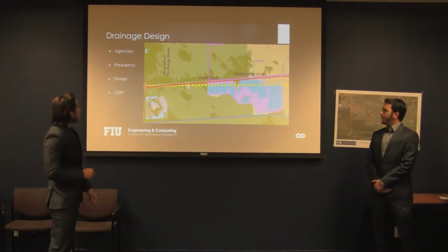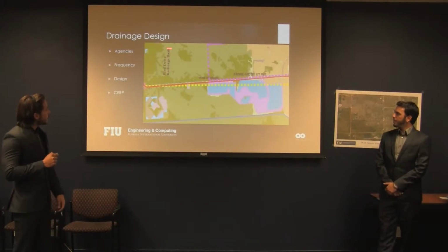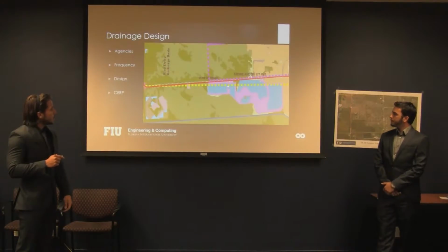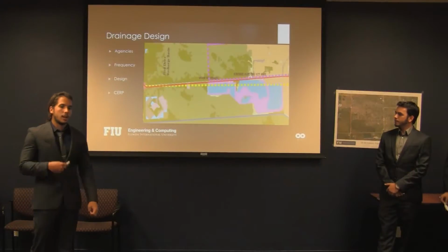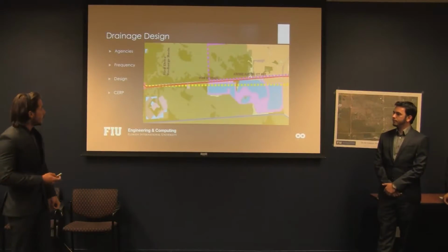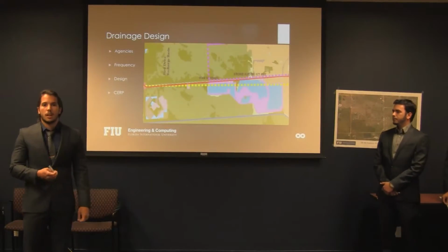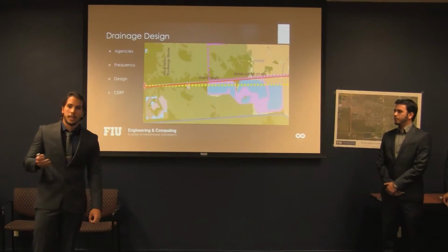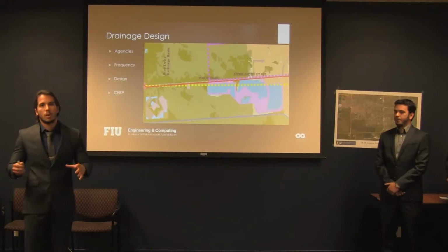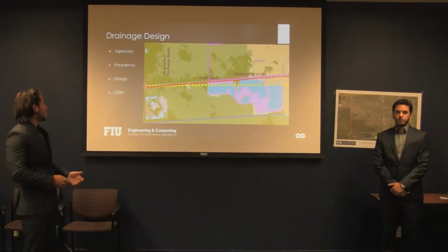This is what I was talking about just now. This is basically the aquifers around this area. These are drainage ponds. This is not what we're using. We thought about 3 drainage ponds in the area in general. And as per our pipe size, depending on the drainage and the area in general, in one of the calculations that we did, we got a 24-inch pipe.